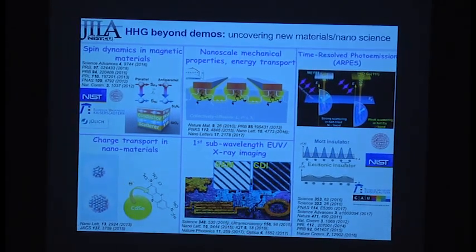What our students found in the lab by just making the measurement, which we weren't expecting, is that if you have nanoscale hotspots with dimensions smaller than the phonon mean free path in the surrounding cold material, they cool faster if you pack them closer together. There is higher energy density per unit area, but we figured out over time that they couple better to the phonon spectrum in the substrate. It looks like a uniform film, and so you can drive cooling very fast.